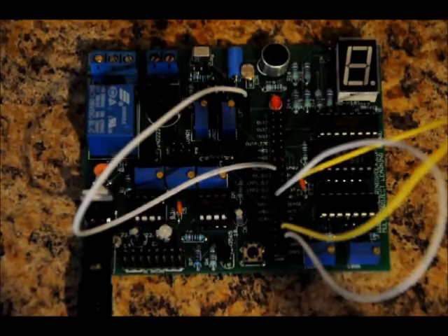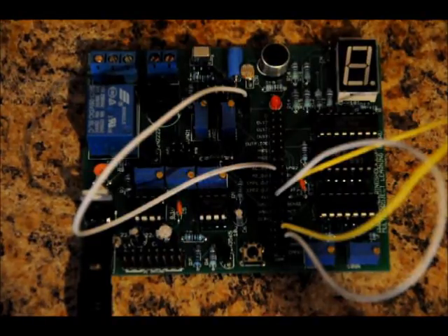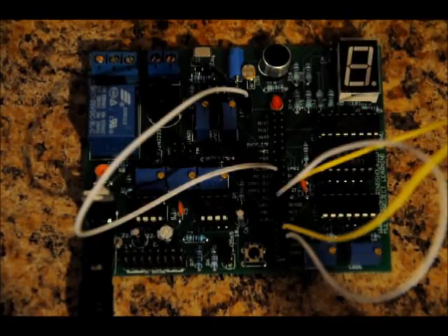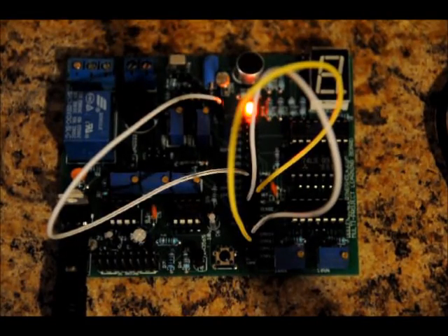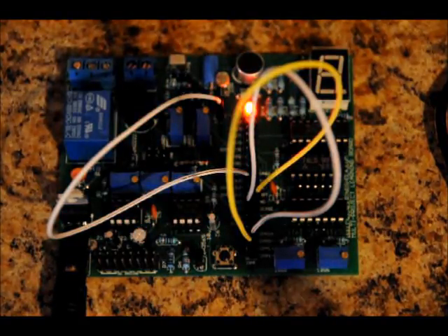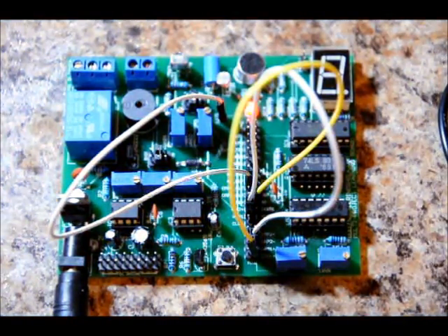Again, I'll turn out the lights one more time. Now, what happens if I switch, like we talked about on the board? What if I put my LDR voltage on my negative input and my 2.5 volts from our variable resistor on the positive input? So I've switched around the logic. Now the LED is on when I've got my light on, and if I turn my light off, the LED turns off. So hopefully that makes sense. It's just a matter of placing two different voltages on a comparator. A comparator compares. It's all it does. Output is high or low.